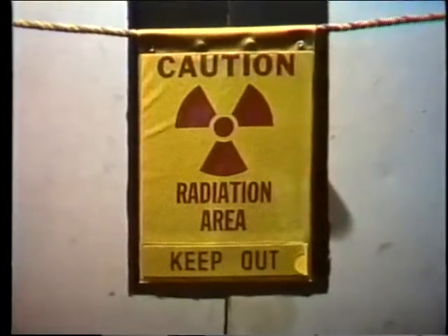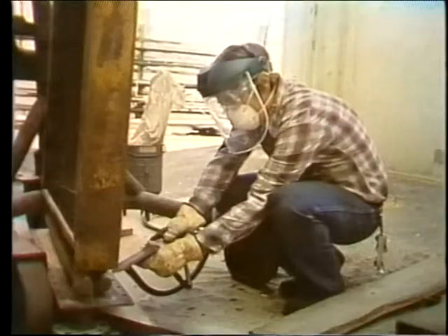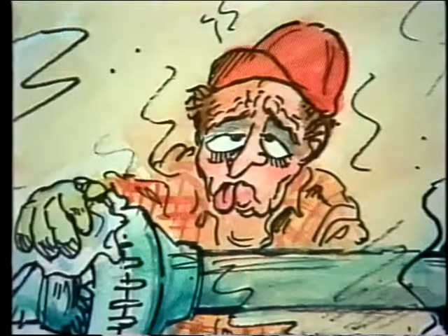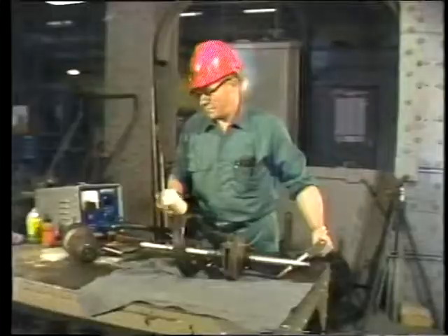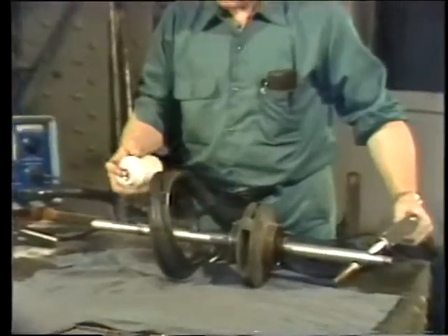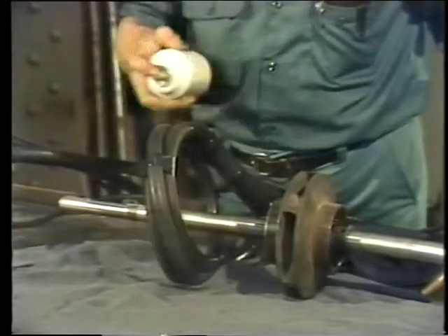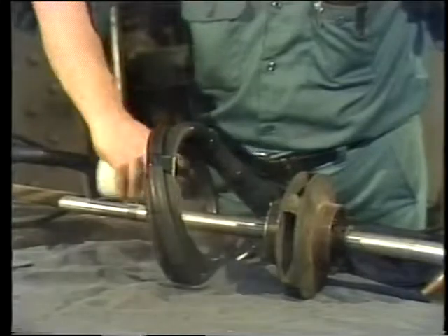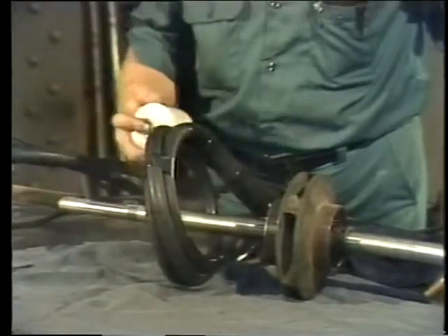With any method of non-destructive testing, safety comes first. Abrasive blasting can be dangerous if someone is careless or forgets to wear their eye protection. And some solvents are flammable or give off fumes that can be a breathing hazard. Aerosol sprays can be dangerous too. The sprays used for dye penetrant and mag particle inspections carry the active ingredient in a fine mist of oil. If the oil gets in your lungs, it can cause serious problems. It can even be fatal.